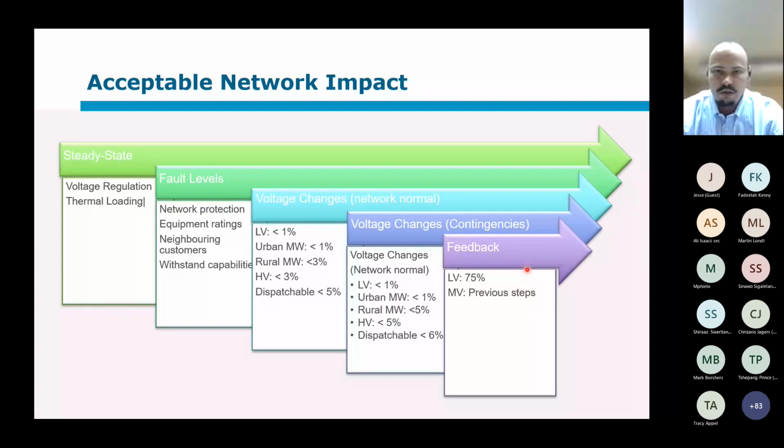So that is what you want to open up the discussion with your supplier, as well as just limit the impact a little bit at low voltage. By the time you get to medium voltage connections, those become less important. Why? Well, there would be a transformer stepping up from a low voltage where the generation occurs up to the medium voltage where it connects to your network.